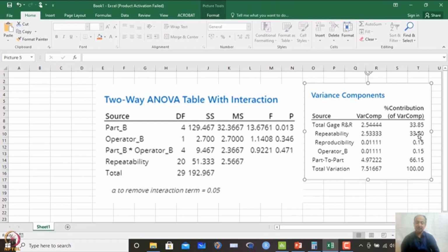So, something is loose in the instrument, like what we said, that some screws or something are loose over here. Something is going wrong, repeatability is not correct. So, we have to send it to metrology to look into what is going wrong. If it were due to reproducibility, operators would be measuring differently. That is not the case; repeatability is the problem over here, and that represents that the instrument has a problem, not the operators used for doing these studies. They are not measuring differently, but the instrument is measuring differently. So, that is an important aspect. It has to go to metrology, and we have to check that one.